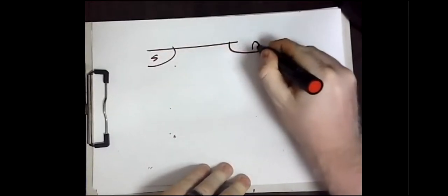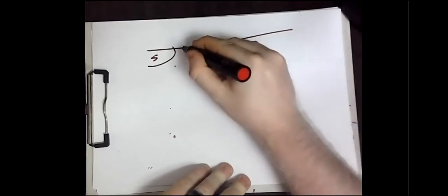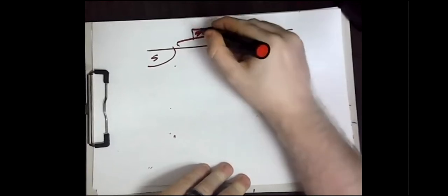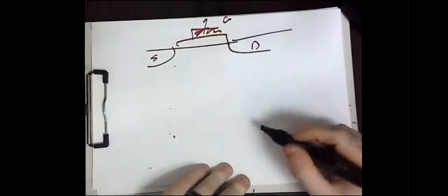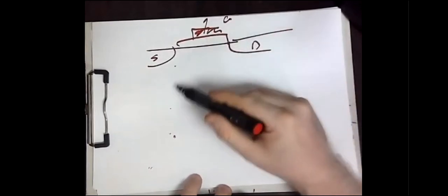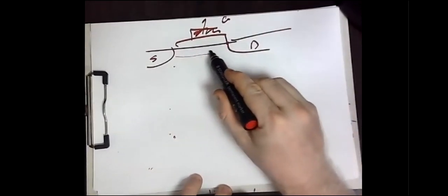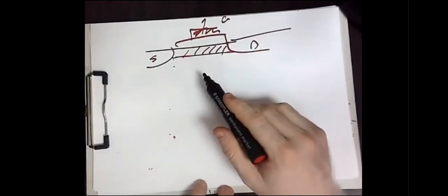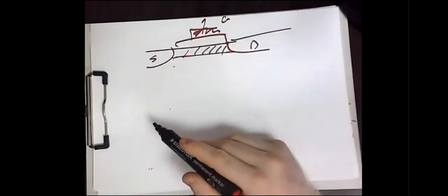As a very quick flashback, we start with this schematic. We have a source, a drain, then we have this oxide layer, and then we have a metal contact where we have the gate voltage. Once you apply a positive voltage here, electrons start to be attracted from the substrate, constructing the channel, or this bridge between the source and the drain. So this is the inverted layer constructed due to the positive charge applied to the gate.